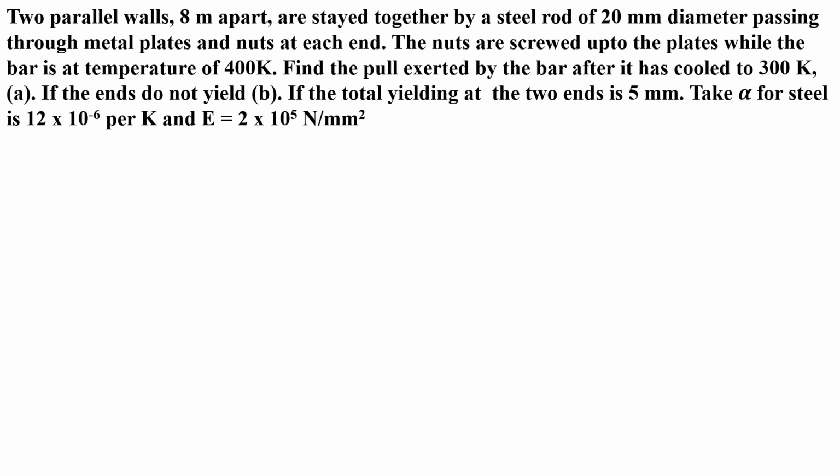Let's see the example problems on temperature stresses. First problem: two parallel walls 8 meters apart are stayed together by a steel rod of 20 mm diameter passing through metal plates and nuts at each end. The nuts are screwed up to the plates while the bar is at a temperature of 400 Kelvin. Find the pull exerted by the bar after it has cooled to 300 Kelvin.